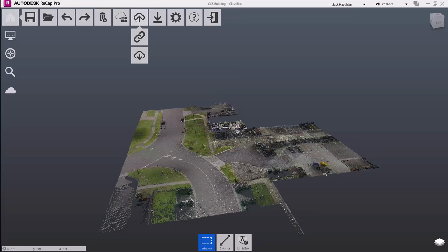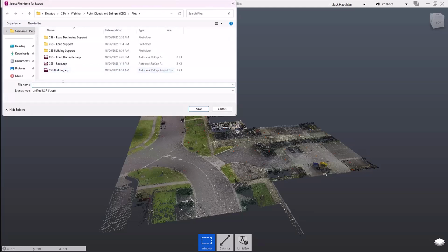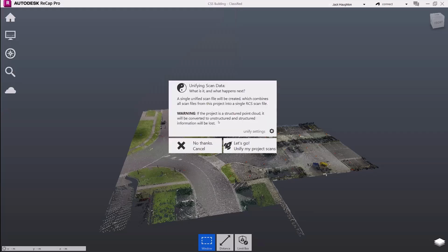along with Revit and a number of other functions, which we'll go through later, and allow you to very quickly draft that up. The other option, if you're working more of a feature survey, you're just wanting to get the basics out and work with them in Civil 3D, I recommend running the export command found here. Export will allow you to export this data out as an RCP file. So we'll call this one CSS new. And we can very quickly push that out.